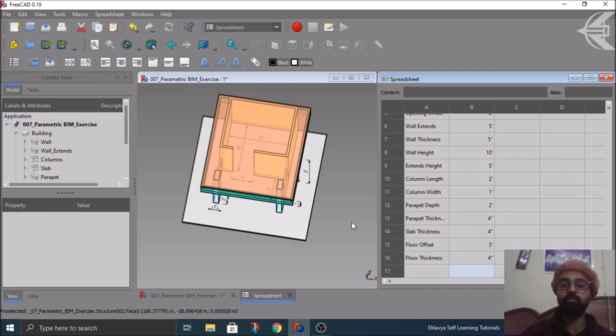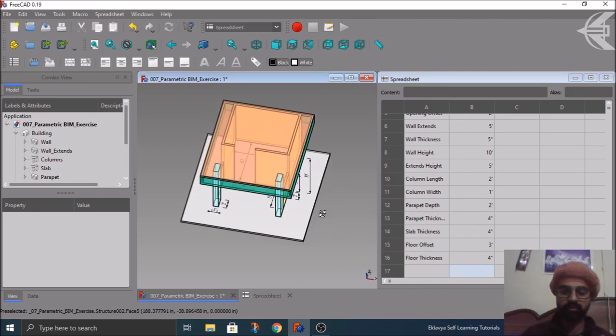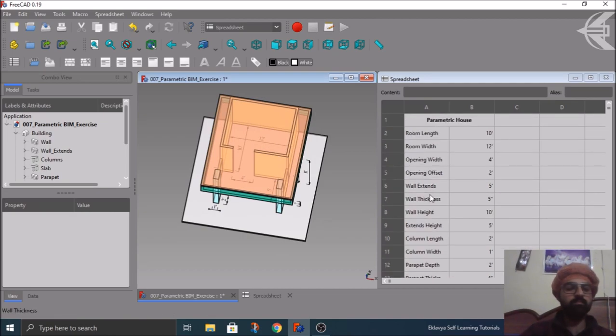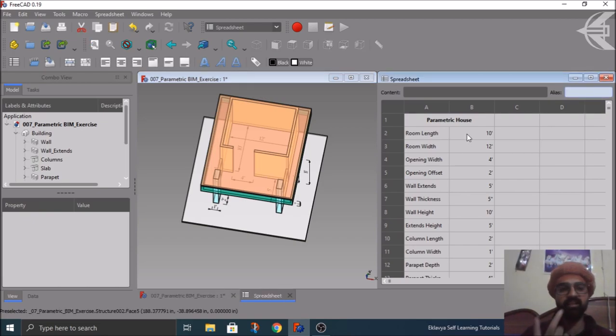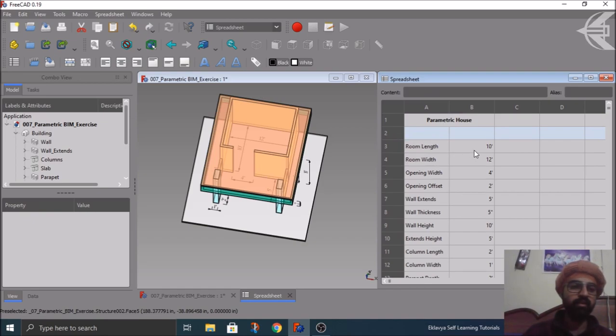Now we'll start linking, but before linking, the thing you need to do here is assemble your overall spreadsheet in terms of units and aliases. An alias is basically a secondary name given to your particular dimension, which makes it easy for you while linking with your constraints. Suppose you are linking it by column B and row 2, like B2. But if you have inserted a row here, this will become B3. So you have to revisit your particular constraint and make changes there.